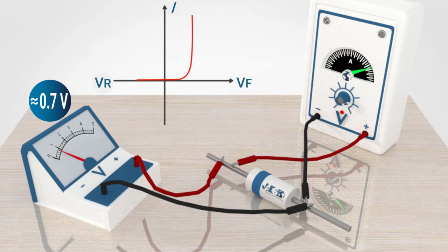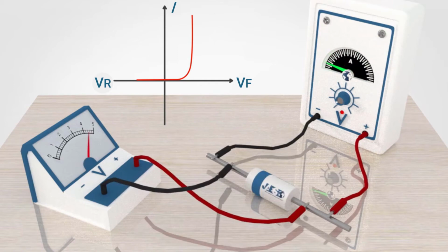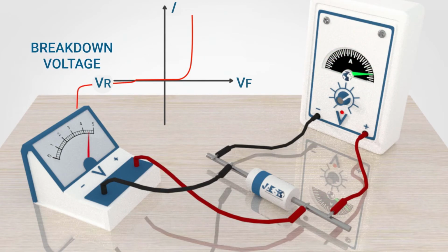This depends on the forward bias condition. In this case, the diode places little electrical resistance. In the reverse bias condition, if a very high voltage is applied, the diode could be damaged due to the rapid increase of the current for small increase of reverse voltage applied.